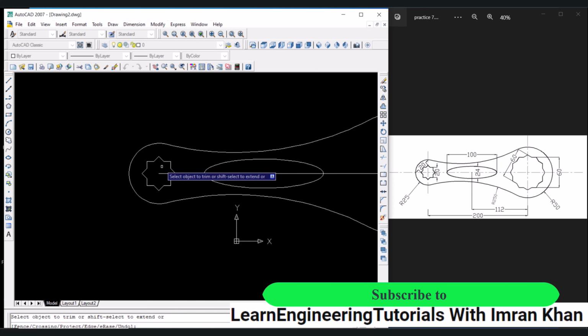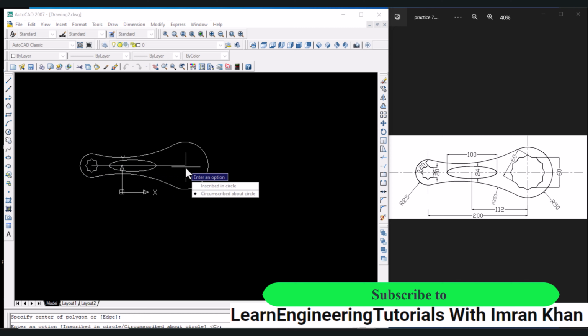the object is drawn. Click on polygon again, this time number of sides should be 6, enter. This should be the center point, click on circumscribed, and now in this direction we have to specify the radius as half of the value given. So the radius should be 30.